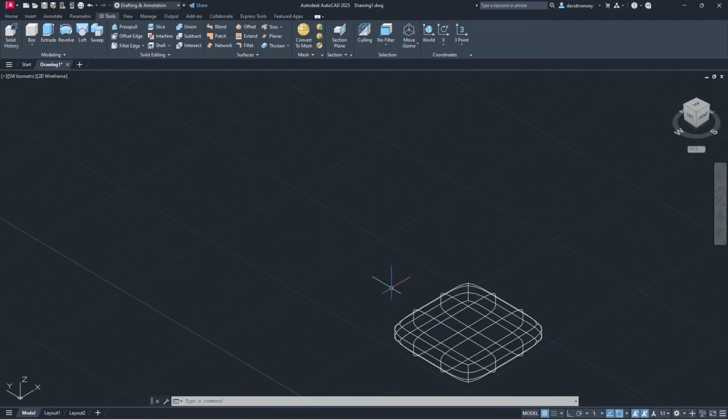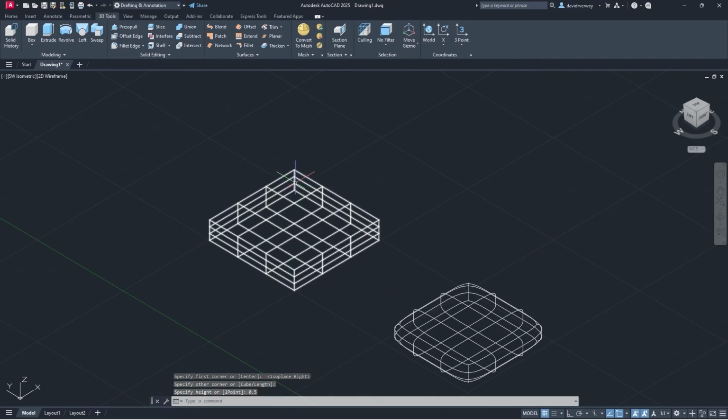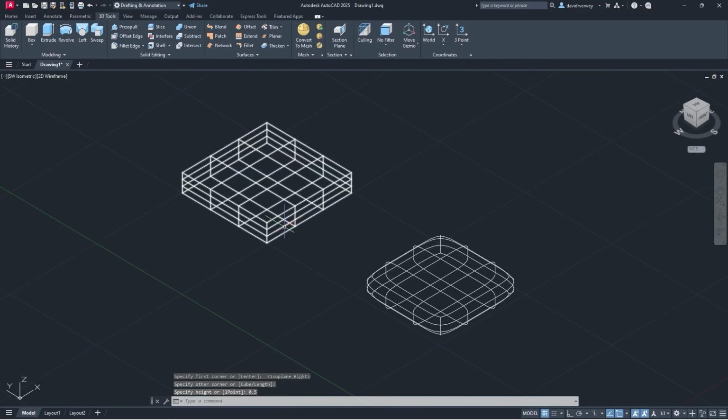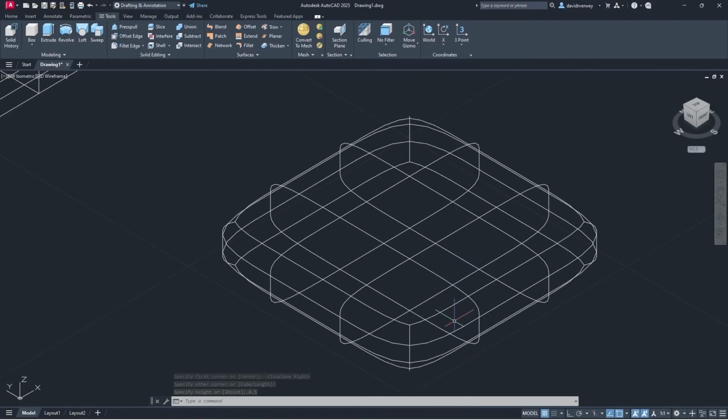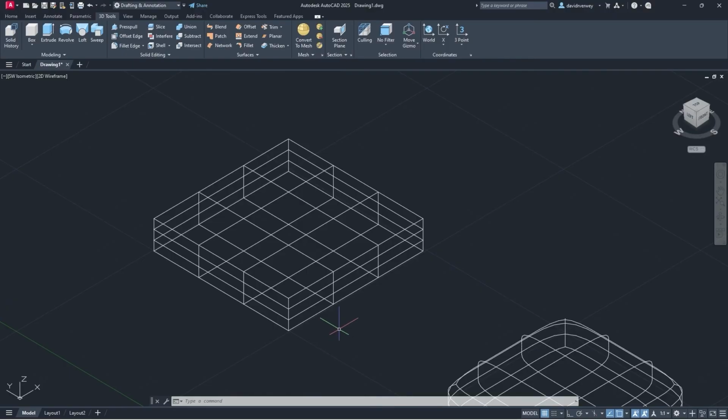But first we're going to create meshes without converting meshes. So what you do is you come here to modeling, and you're going to see there's a variety of meshes you can already make. We're just going to make a mesh box. You take this, you draw it, and you can see that it looks similar to what we had before. Come up here, we're going to make it 0.5 in height, and you're going to see that this mesh is more of a square than the one that we previously had, because that one we converted using a different tool. Over here you're going to see that we have a variety of different mesh sections, more than we did in the previous one. And what this does, as I explained before, is allow you to pull things out and do things with that. I'm going to show you how to do that in a moment.